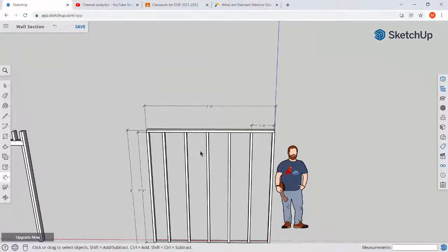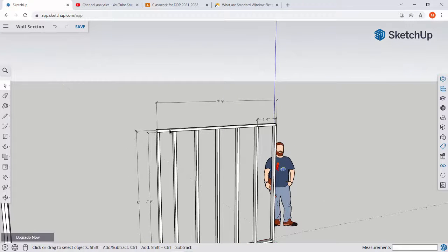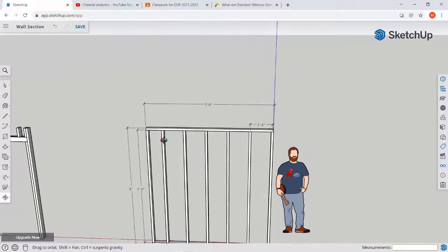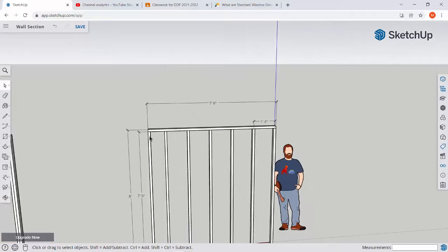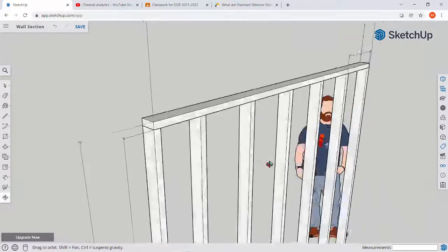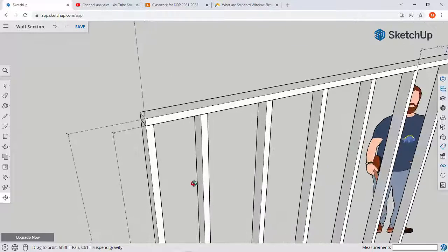But wait, there's a weird thing here, because it would be more nicey nice if this was actually 8 feet long. It has to do with the way that your sheets of plywood and drywall are constructed and made. They're going to come in sheets that are 4 feet by 8 feet. So if the center of this stud landed directly on 8 feet, boy oh boy, that would be really convenient for a builder.